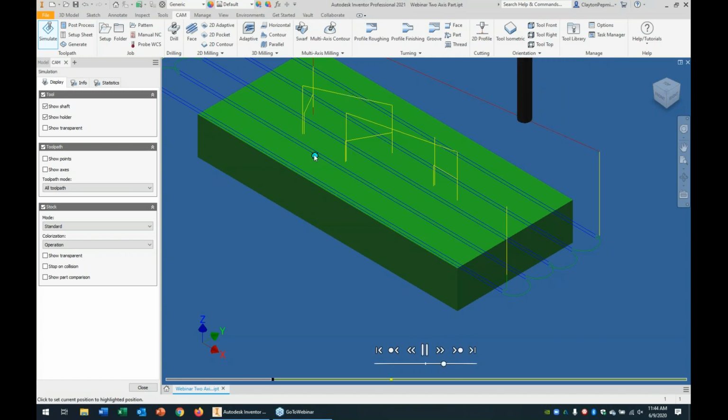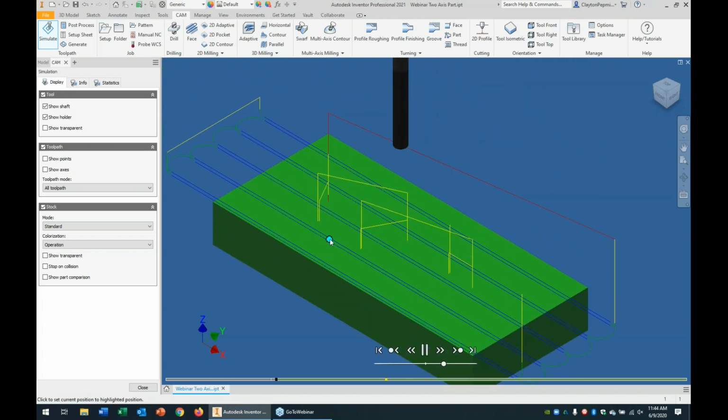So I want to watch the cutter and how it approaches this pocket. Yes, I did tell it to plunge. I know some people don't like plunging, but notice the spiral approach. You have a certain chip load on that tool. As it gets into the corners, it's not diving into those sharp corners anymore. See it taking the sweep or large circular approach to cut that out? At no point in time does it ever get buried into those corners. It's just going to repeat that layer by layer.